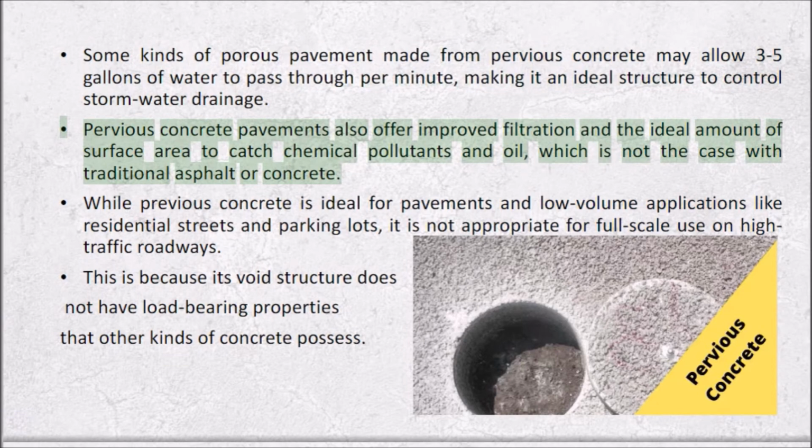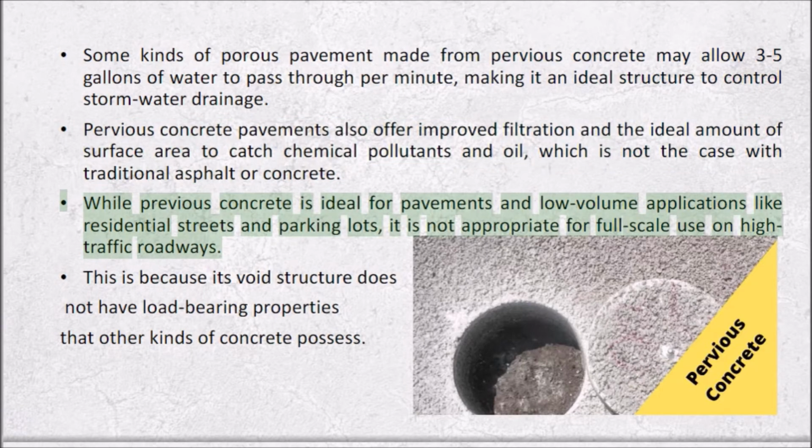Pervious concrete pavements also offer improved filtration and the ideal amount of surface area to catch chemical pollutants and oil, which is not the case with traditional asphalt or concrete. While pervious concrete is ideal for pavements and low-volume applications like residential streets and parking lots, it is not appropriate for full-scale use on high-traffic roadways.